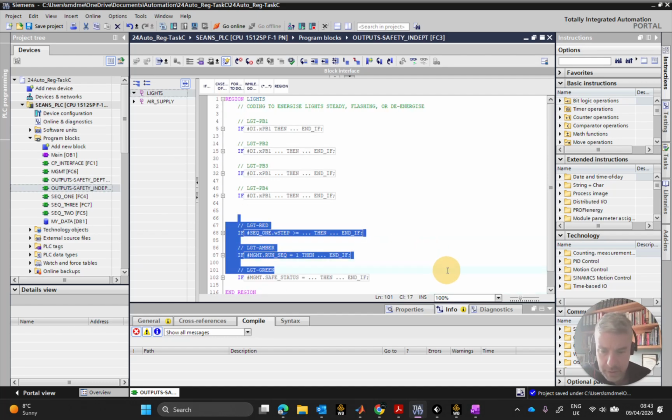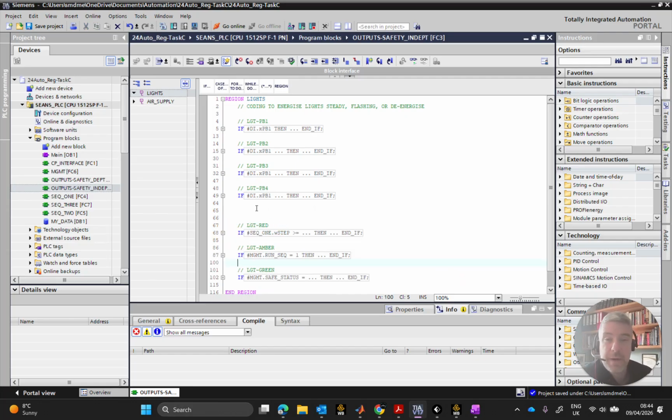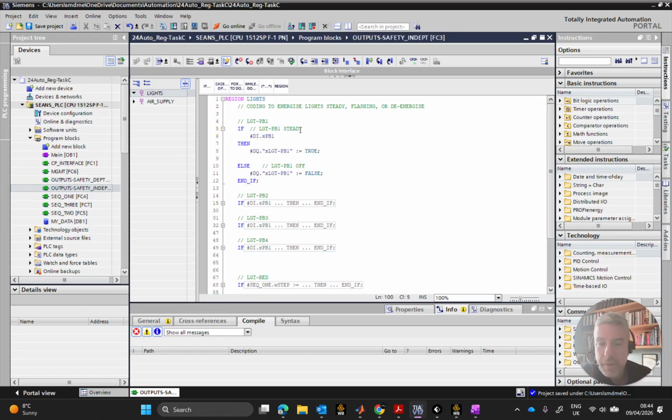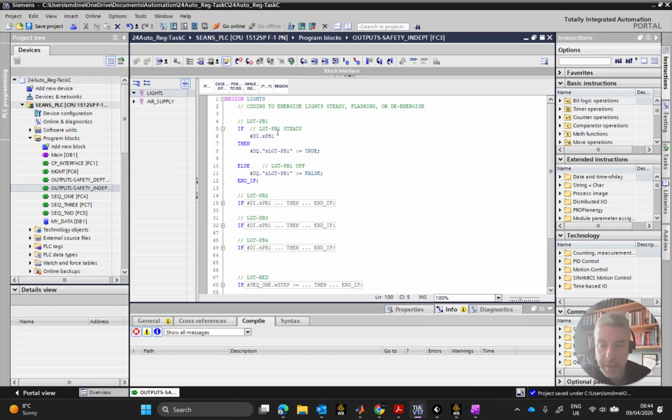Now, I can broadly ignore them, right? So I don't even have to comment them out. There's no mistakes. It doesn't matter if they fire on or fire off. Once they're not wired and there's no lights that come on, or you don't miswire anything, you're fine. The PB1 light, right? I have 2 states for the PB1 light. It says nothing in here about blinking at 1 hertz or at any other hertz for that matter. I want the PB1 light to be on steady.